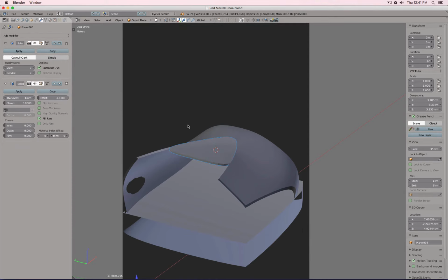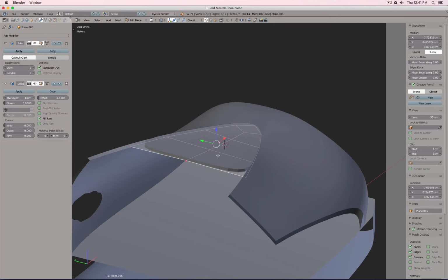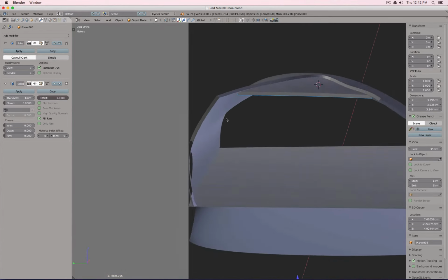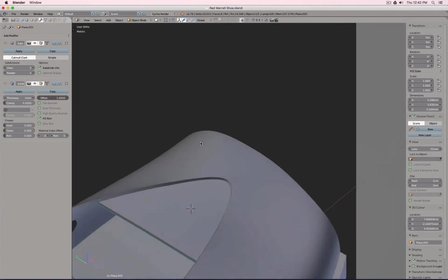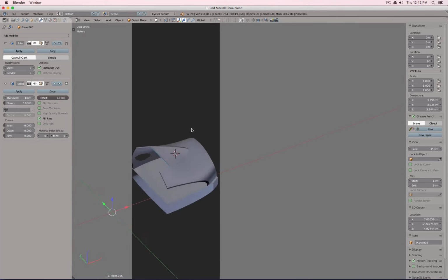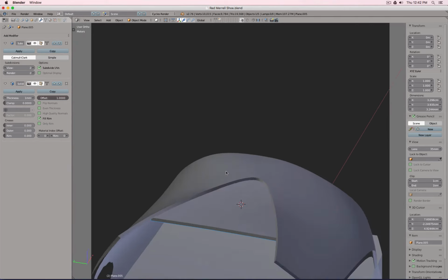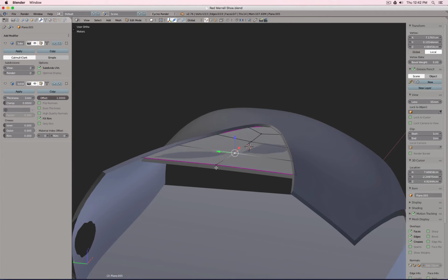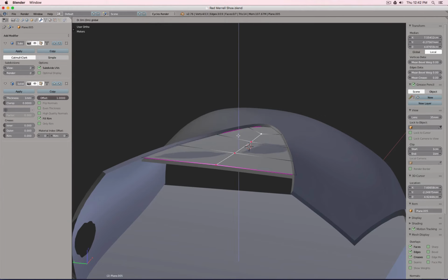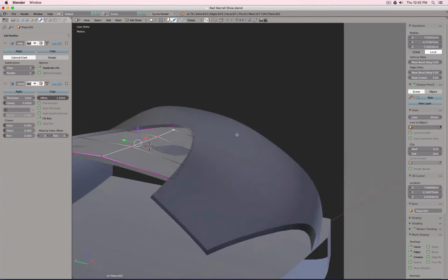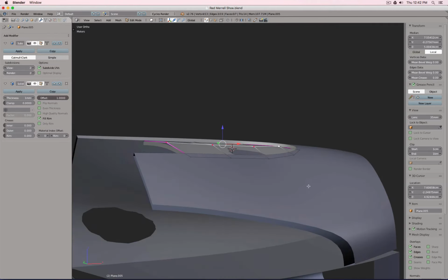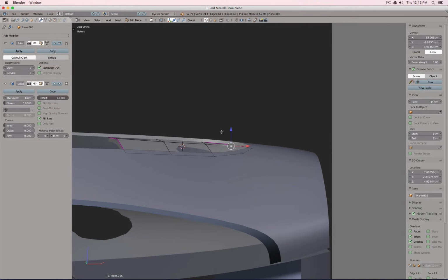Subdivision surface, and then our solidify, and then this here we all sharpen, Shift E and 1, and this can actually go the opposite direction because it's inside. Okay, and then it pretty much looks the same way as like an inlay. And then if I want, I can dome this out a little bit. Maybe this a tick lower, this maybe a tick more.